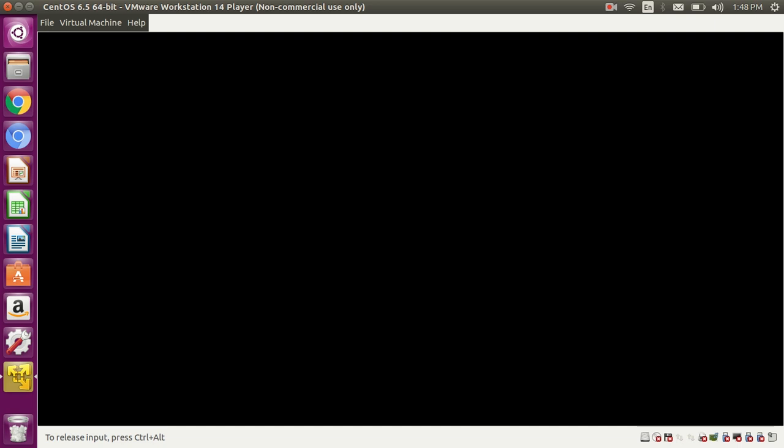So here the enable is 1. This 1 will come out. This enable may change here, that means a glitch may happen. But what will level 0 do? It will not impact the latch. That means it will maintain the previous value, whatever we had read. So even if enable goes 0 here, the clock duty cycle will be maintained. And at this point it will give the enable signal. What is the enable signal we have? We need 0 itself. That's how we give the full clock, whatever period and duty cycle we have now, to the output. I think you got the point. Otherwise, you might be confused here.